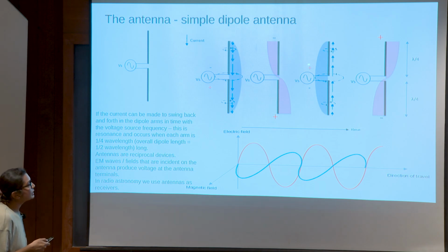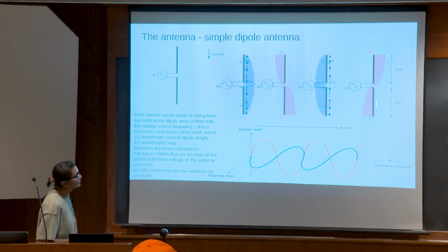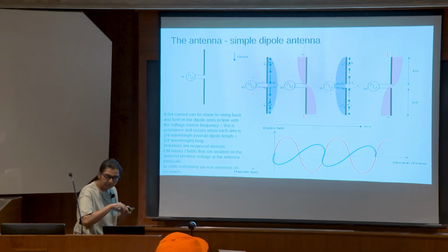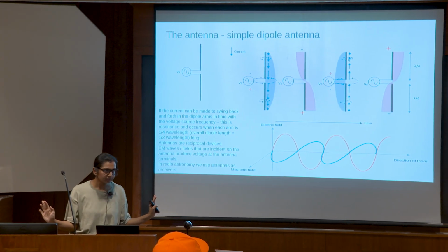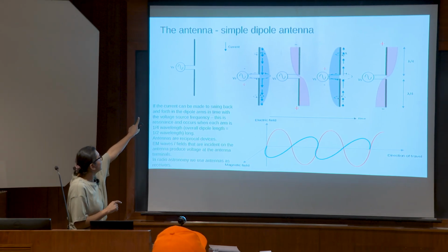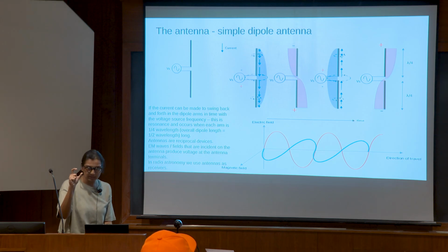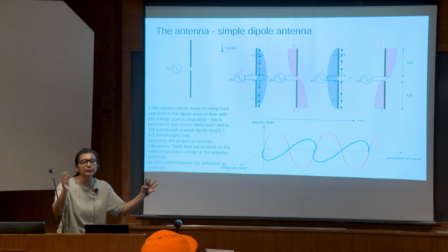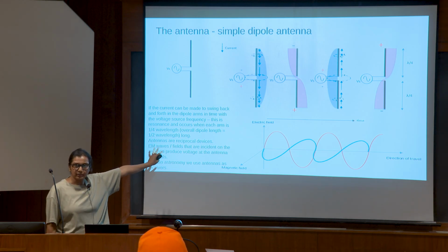Similarly, next time the charge polarity is reversed in the voltage source. So you have currents going up that way, and then you have buildup of charges, okay, and then when the current polarity flips again, electric and magnetic fields are released, okay. So hence you have made some piece of wire connected to an RF voltage source, something that's pushing out electric and magnetic field lines, okay. So this is an antenna as a transmitter.